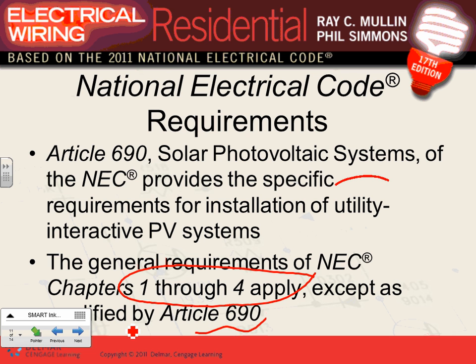Electrical utilities will require you one requirement for the interactive system. They only require you one requirement. Your interactive photovoltaic system has to be rated, UL listed. If you lose the power, your interactive system must shut down.